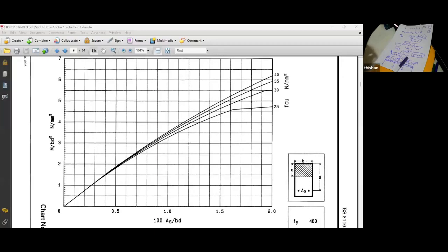Can you understand that, Bandhu? Why I have this magic number 3? Yes, sir, it's a bit clear now. Yeah, because with this 3, now I need this little reinforcement. If it's 2, even less. Why? Steel is very expensive. So why do you want to save concrete when the expensive material is steel?